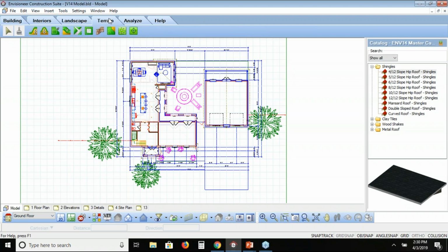You'll notice at the bottom of the screen that I can type in the actual northing and easting and distance information with my plan, but I should be able to incorporate that site plan in very quickly as well. Not only just the 2D site plan, but site information as well. So if I have the topo information available from a field recorder, I should be able to import that. And that will take the terrain and add in the 3D mesh. So when I'm out in 3D, I can see the different levels of the terrain.